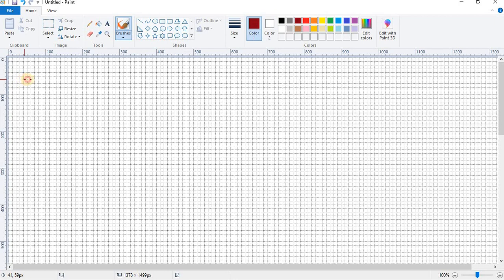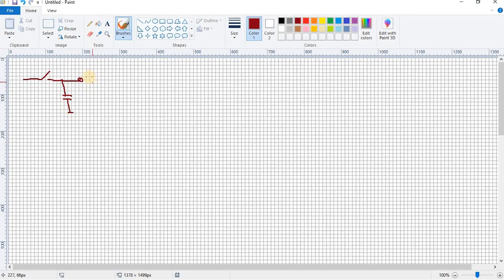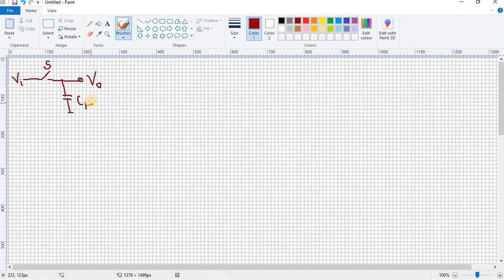So in the sampling circuit, you should have a switch which is used for the sampling aspect, right? Then there should be a capacitor. This capacitor will act as a holding capacitor, right? In this, this particular terminal can be assigned as Vout, the output voltage. This will be assigned as Vin, where the input voltage is applied. This should be the switch, and this should be the capacitor, which is generally defined as the holding capacitor, right?